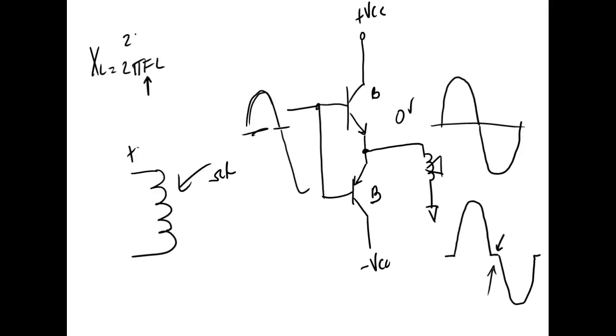These transistors have to be what we call complementary pairs. They've got to be matched. So, of course, we couldn't get much power out of it. Most of your transistors have what they call a complementary pair. So up here, this might be a 3904. Down here, this would be a 2N3906. And the 3904 and 3906 are a complementary pair.